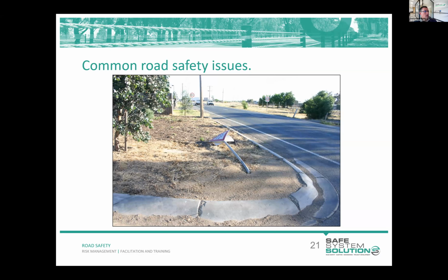Here we have a knockdown sign, which can be a sign that there isn't enough space for a turning vehicle. Another common example is the keep left sign on a splitter island at an intersection. You often see those signs knocked flat or installed with rebounding posts.